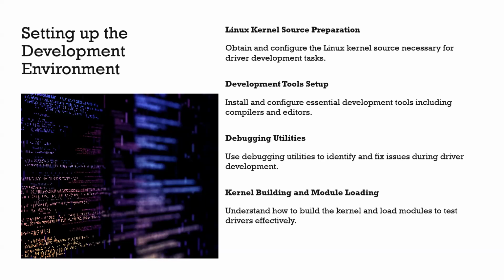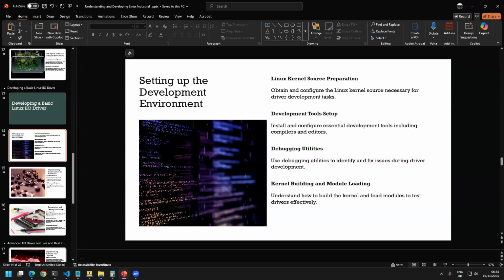In your development system, you can install the latest version of the kernel and build your driver against that kernel, and you have to transfer that kernel to the target.